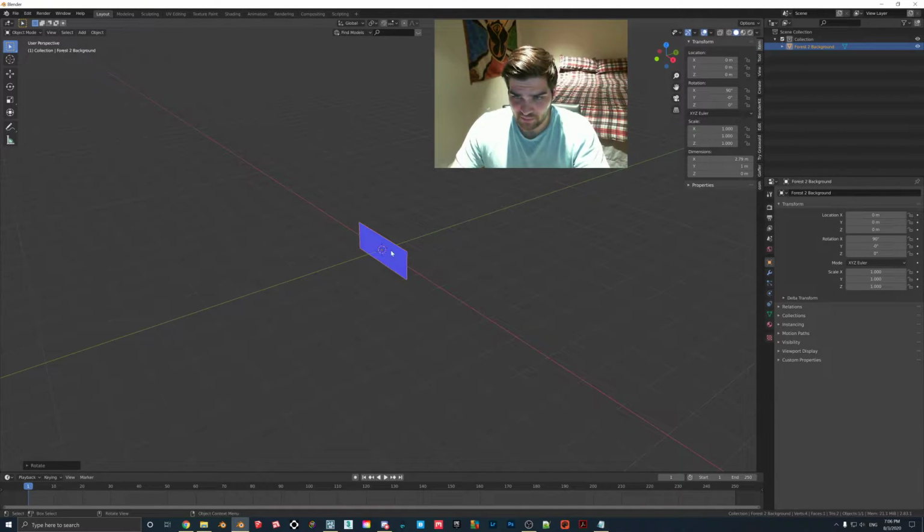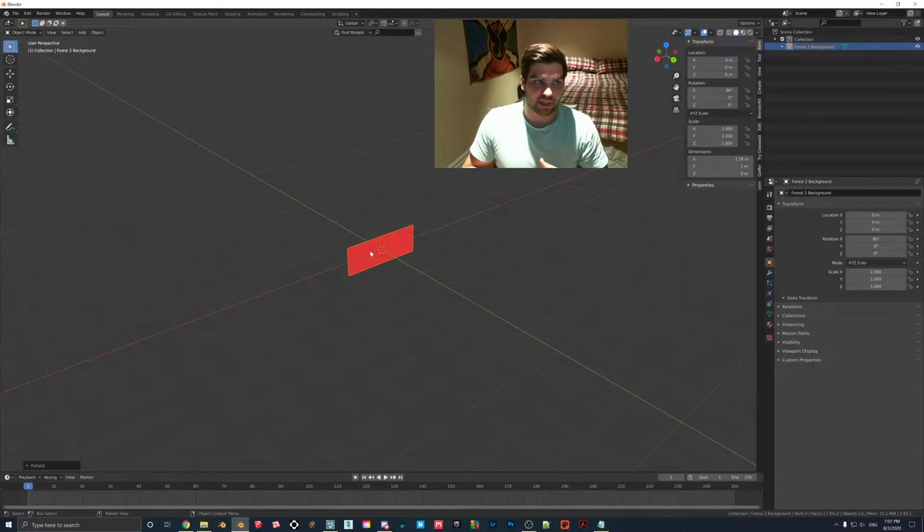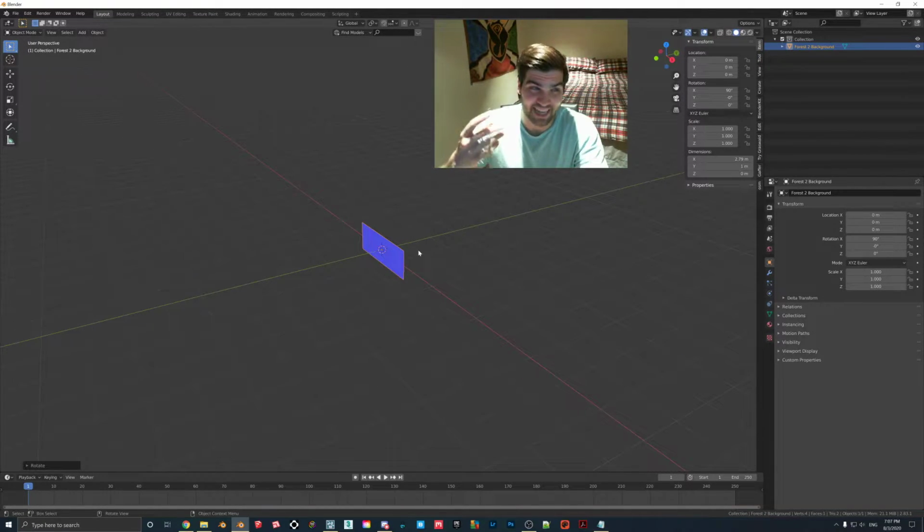But basically in Lumion, it will only show the blue side. If we went like this in Lumion, you're going to see right through it. And this is the very important part because the light will go right through it. Like you won't get the shadows, which is very important. Because if it blocks the light, then you just get this really dark scene. And no matter what you do, you're not going to get light into your scene. You won't get basically the effect that you want. And that's no good. Partially why I'm showing you this is because it's much more important when we're going to do the spherical one. For this one, you can kind of just rotate it and get away with it, but you can't do that. Or you could flip it, but you can't do that with the spherical one.